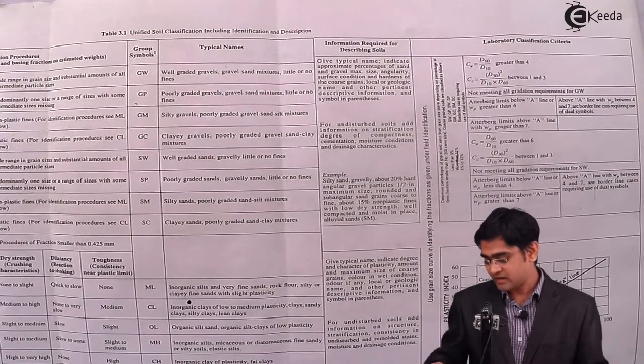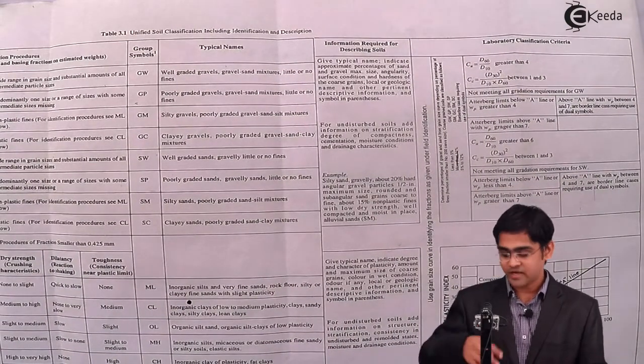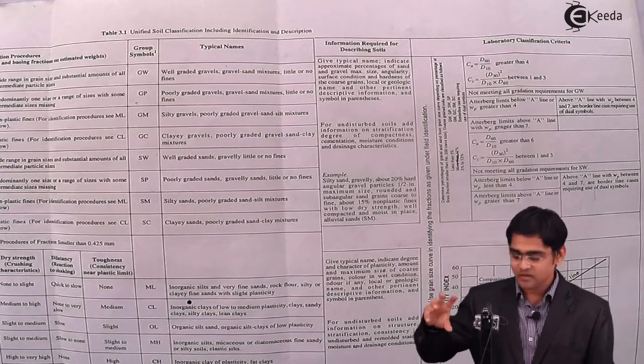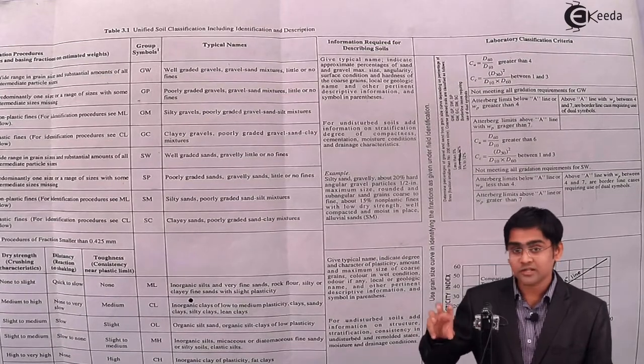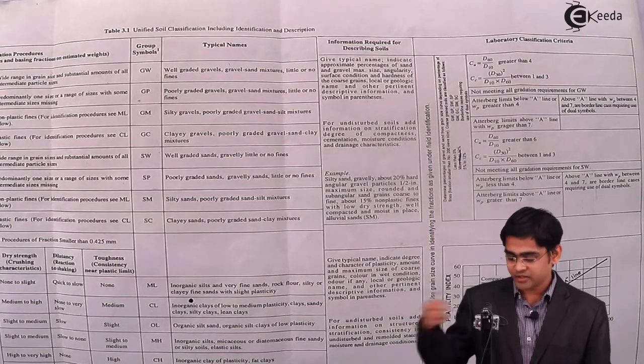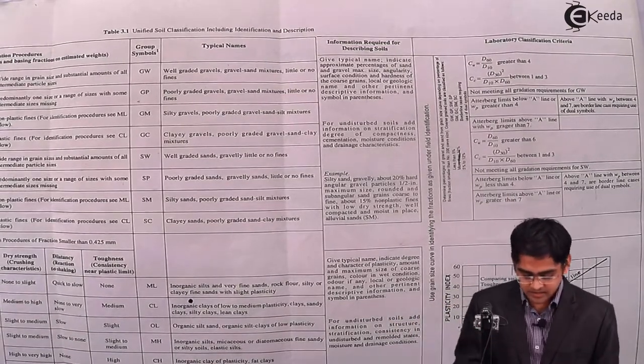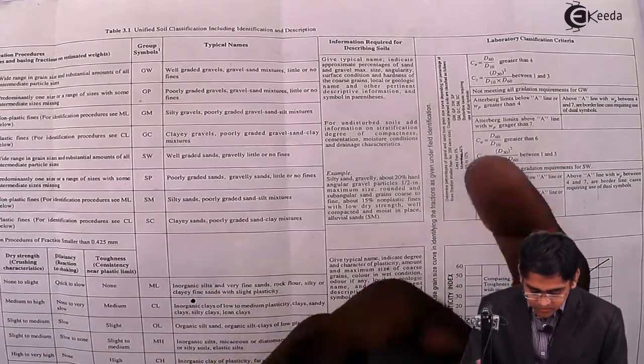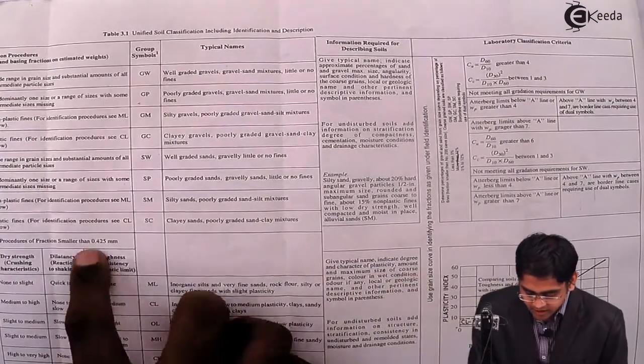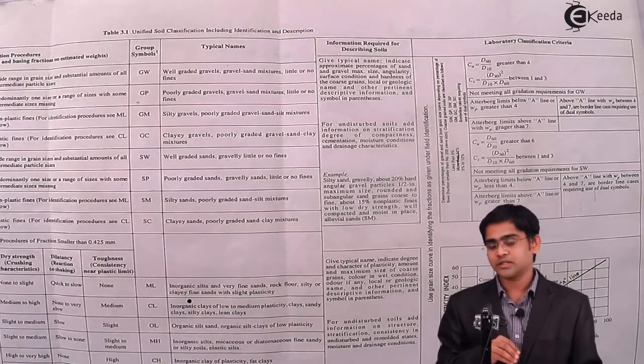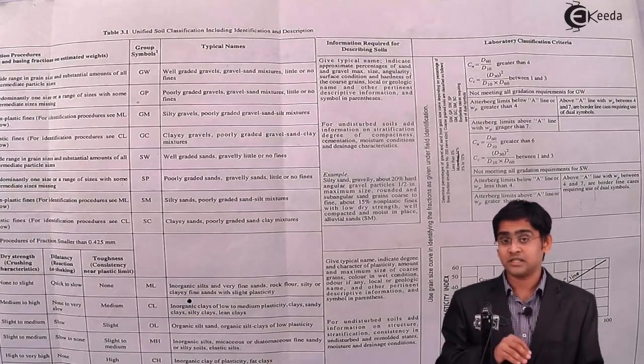Therefore, for a higher liquid limit, there are higher chances of compressing the soil, or higher will be the change in volume from liquid limit to its dry state. Also, with reference to toughness, it is nothing but the shear strength of a soil at plastic limit.